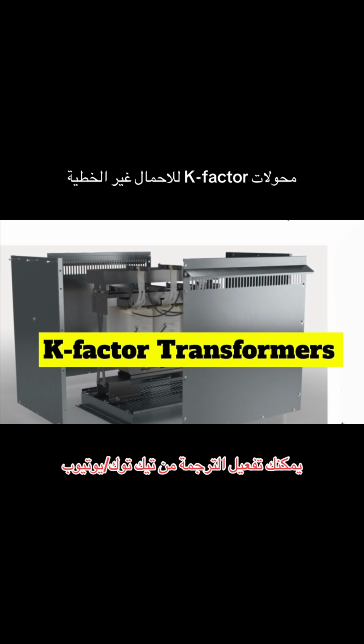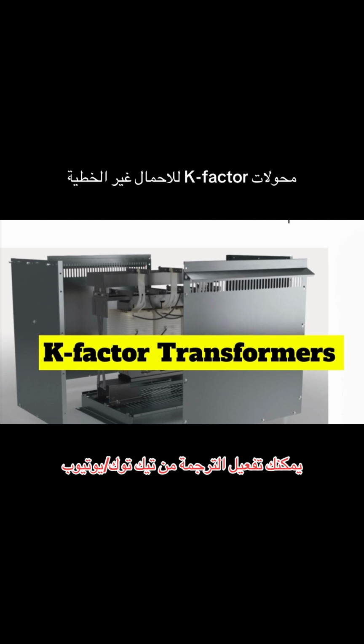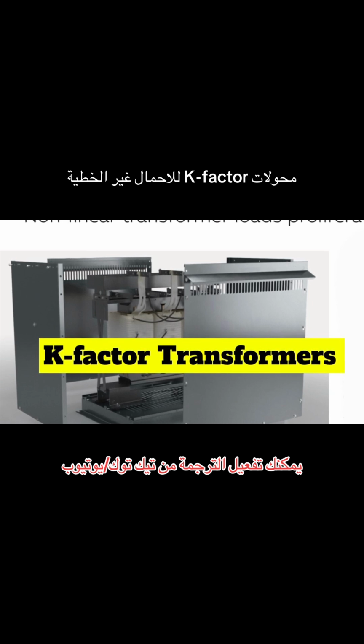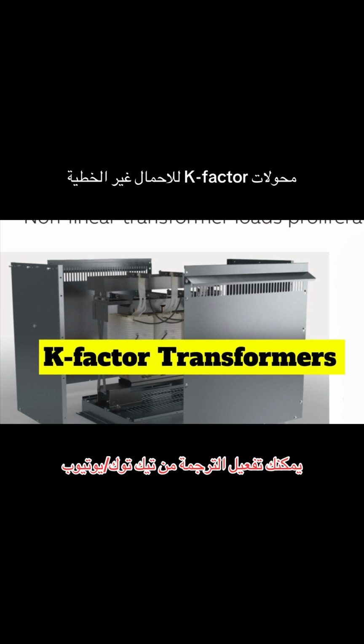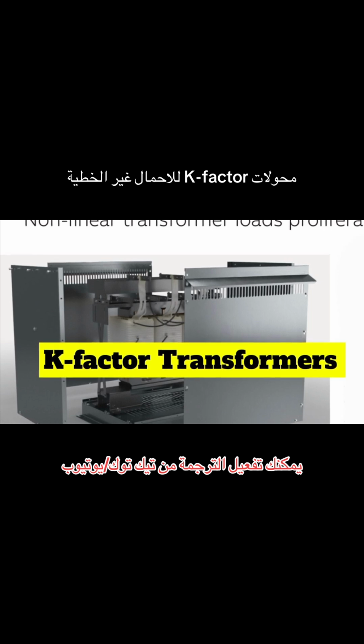All right, let's wrap things up with a quick summary. We've learned that our energy-efficient electronic devices, while great in many ways, introduce these unwanted harmonic currents into our electrical systems. And those triplen harmonics are especially troublesome because they add up on the neutral wire, creating extra heat. To deal with this, we have K-factor transformers, which are specifically designed to withstand this additional heat. They have things like oversized neutral bars and other internal modifications that help them dissipate the heat. And that K-factor number you see on the transformer's nameplate tells you how resilient it is to those harmonic-induced heating effects. That's a great summary.